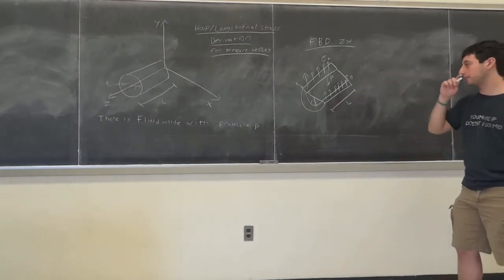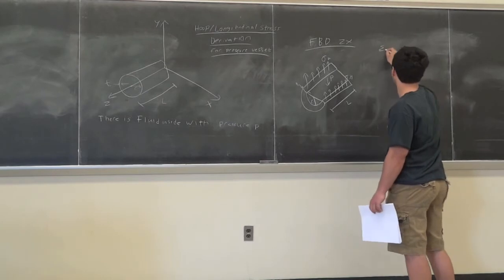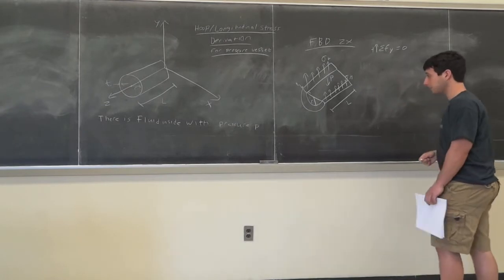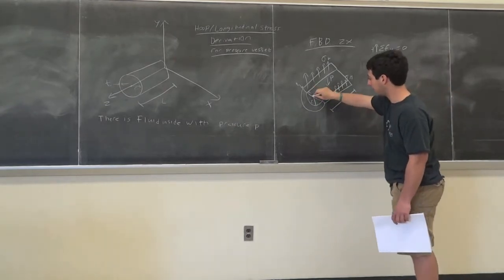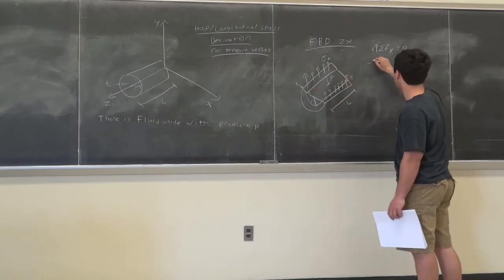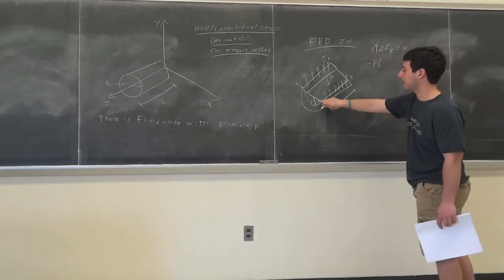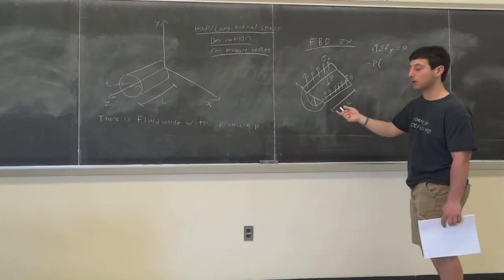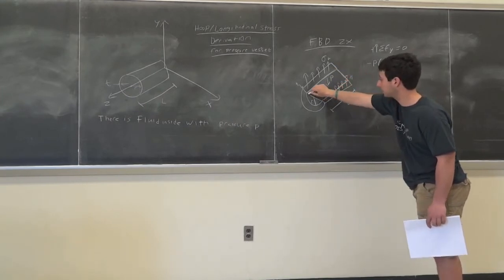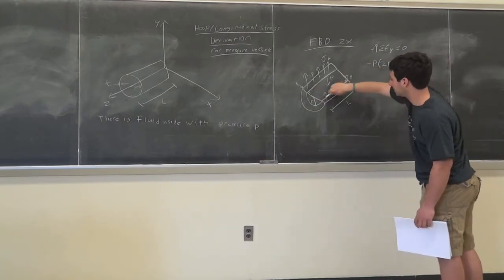Okay, so we're going to have to do a force balance, right? It's a simple force balance. The forces are only acting in the y direction. So let's sum the forces in the y direction to be 0, taking upwards to be positive. All right, so P's acting over this area over here, right? So P is facing downwards, so it's minus P times its corresponding area. What's its area? It's L times 2R, right? L times 2R is the area of this rectangle over here. You guys see that? So it's 2R, that's this distance, times L is this distance.